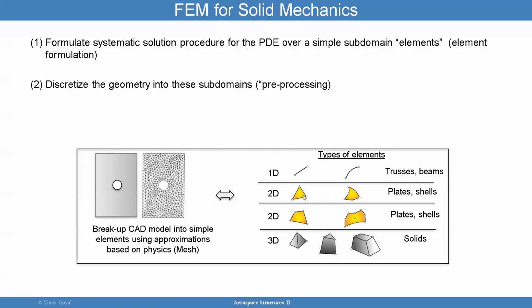I want to make sure it's clear that this triangular element is of lower accuracy than this triangle element here with mid nodes, and the reason is because you have more degrees of freedom. The solution of partial differential equations is really accomplished by assuming a polynomial distribution that's able to basically approximate the solution over the triangle. And the same thing goes for this one here. So the triangle here on the right hand side has more nodes, so you're going to have a higher order polynomial that's going to be better at capturing the response of that triangle.